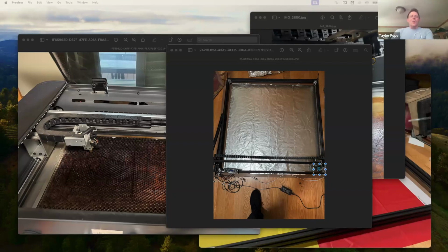When you are working with a laser, there are two main modes you'll be working in, as I just touched on: raster images and vector images. A raster image is an image that is made up of individual points. This works much like an inkjet or laser printer, where it will scan back and forth.